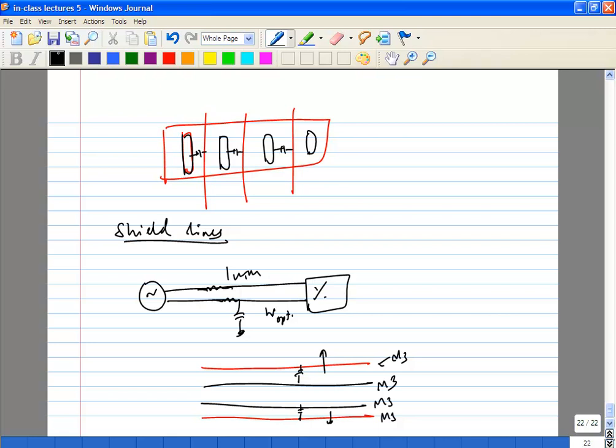But remember, this distance you can actually control. The vertical distance between the metals you cannot control. So typically you don't prefer to add a shield on the bottom. Okay, if you are going to add, you typically add it on the sides. So which is why you're not going to add on top of it, you're going to add to the side.